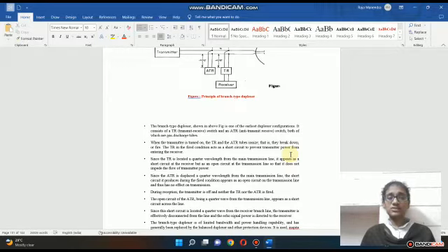When the transmitter is turned on, the transmit receive and the anti-transmit receive tubes ionize. That is, they break down or fire. The transmit receive tube in the fired condition acts as a short circuit to prevent transmit power from entering the receiver.